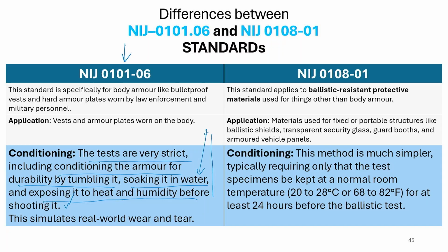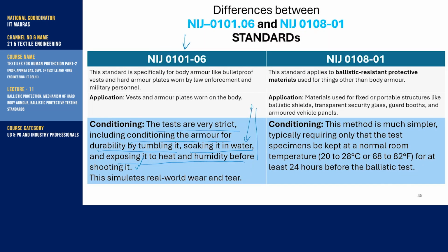We have to first condition it like in normal wear situations, like tumbling it, soaking it in water, and exposing it to heat and humidity, which people normally experience during operation. So to simulate all this real world wear and tear condition we have to do this.